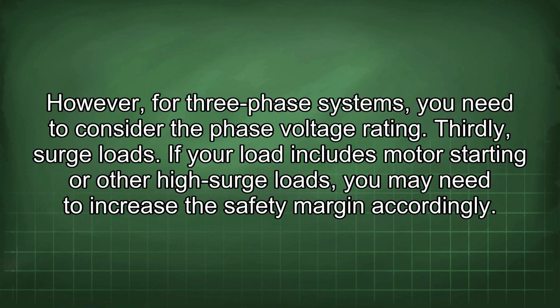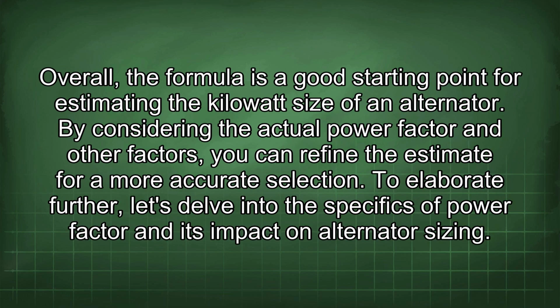Thirdly, surge loads. If your load includes motor starting or other high surge loads, you may need to increase the safety margin accordingly. Overall, the formula is a good starting point for estimating the kilowatt size of an alternator. By considering the actual power factor and other factors, you can refine the estimate for a more accurate selection.